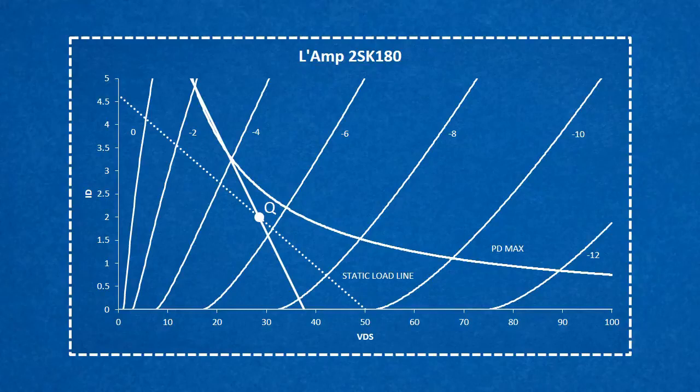Now back to the operating point. Where we place the operating point depends on our design priorities. If we're primarily concerned with maximum voltage swing, we'll probably place it somewhere near the middle of the load line. This is a general cookbook approach. Draw the load line, place the Q point in the middle, and go for a coffee. There's nothing wrong with this approach, and it will maximize the power we can deliver to the load and give us symmetrical clipping.